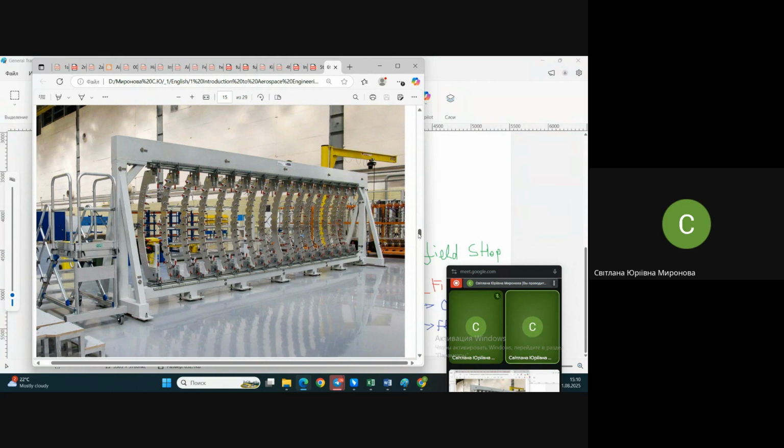How to provide it? One of these techniques of providing coordination you certainly already know. As you are not first years, you already know such things as fits and tolerances. Accuracy and assemblability are provided by using interchangeability, by using the approach of fits and tolerances. When you normalize the size deviations, they are called tolerances. You appoint tolerances and follow these tolerances. When you normalize sizes, and due to following the ranges of deviations of sizes, you provide final assemblability of objects. It works great, if not for one important peculiarity of aircraft, non-stiffness of parts.